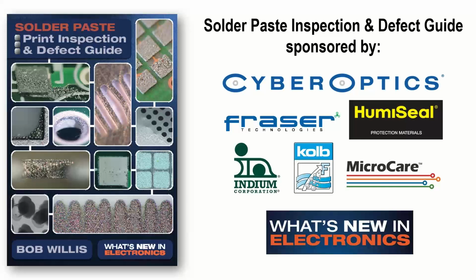Okay, what is the best cleaning profile to use for automatic under stencil cleaning dry wipe? Again, Hamid, thanks for the question, but listen to what I said earlier. It's really doing some trials yourself. I mean, I could say to you, clean every 5 boards and do a wet every 6th board, and then every 5 boards dry. You know, you could have different combinations. You've obviously got to have wet and dry wipes, and then possibly another configuration depending on your printer. But again, you've got to do those trials yourself.